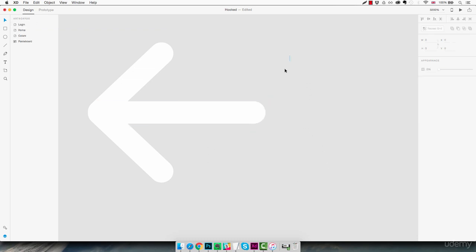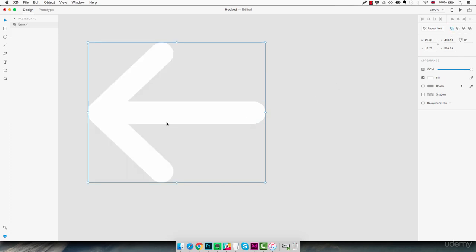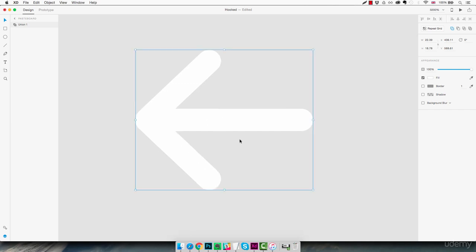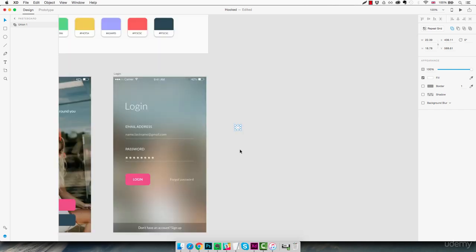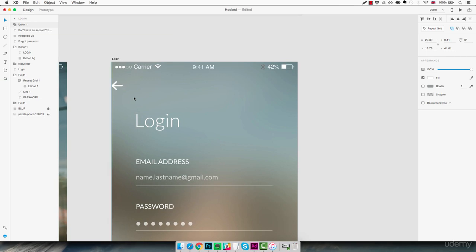Once this is done, we're just going to select all the 3 layers we created, and we're going to hit this button, which is the add function, which basically merges all those shapes and creates one unique shape that you can reuse in your design. And we're going to move it all the way to the top. About 20 pixels from the left border.